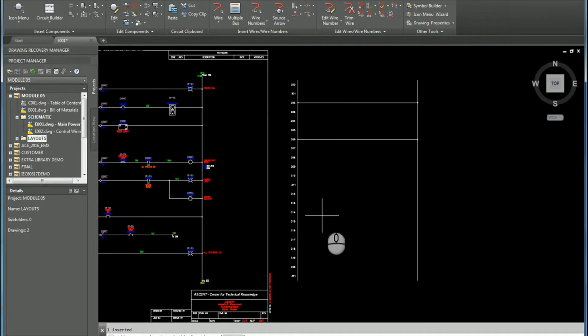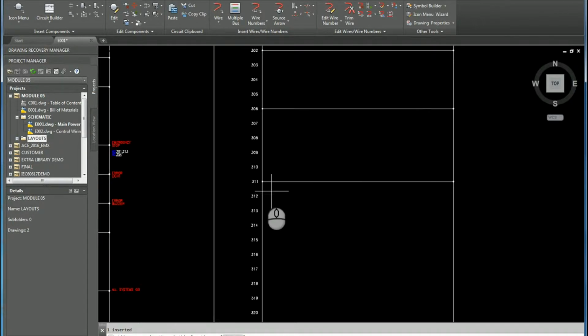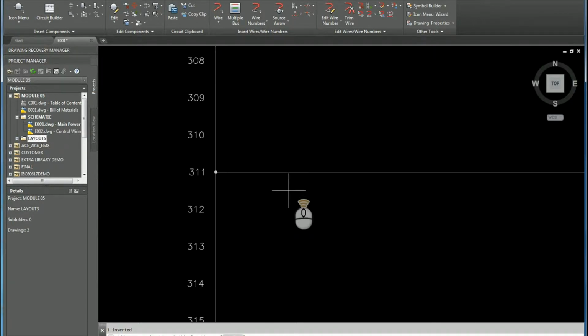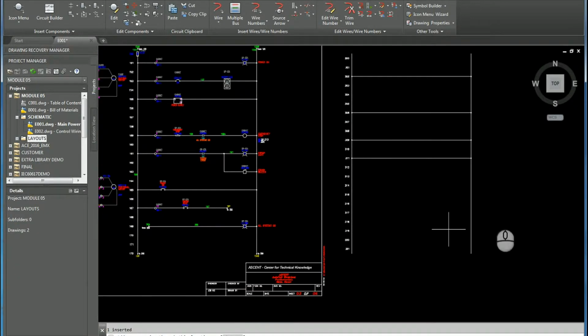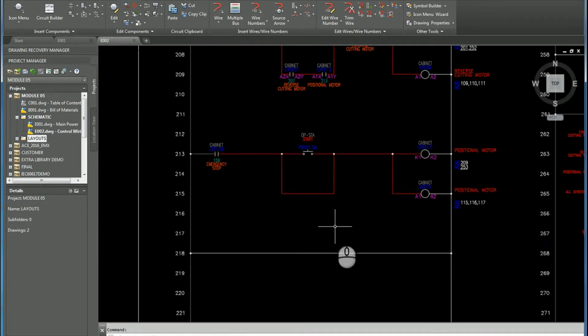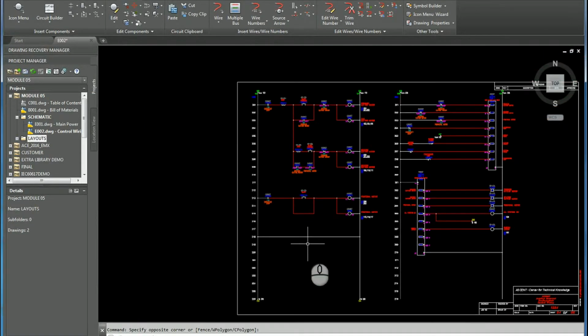Snap in between the two vertical wires, and what we will get is a rung, and it goes ahead and puts my attachments to it. It also will choose the closest reference number, so I don't have to be exactly precise whenever I pick for 309 there. Great feature. So let's go over to my control drawing now. I've added a rung here.